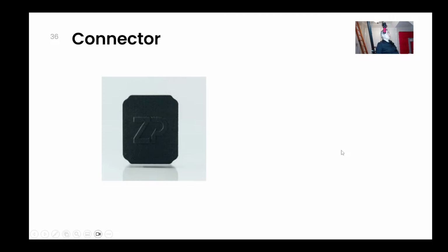If you're not going to use our Kate potentiostat, you will need a connector. So I'm going to put a connector here as well, because the connector will go between your potentiostat and our screen printed electrode. The screen printed electrode I've just linked is 7mm wide, so make sure you get the 7mm connector. And the link here will show you that we've got connectors that will take 2mm banana plugs, 3mm and 4mm. A lot of people, if you're using an Autolab potentiostat, those are 4mm. If you're using PalmSens potentiostats, those are 2mm. So make sure you size the connector accordingly.